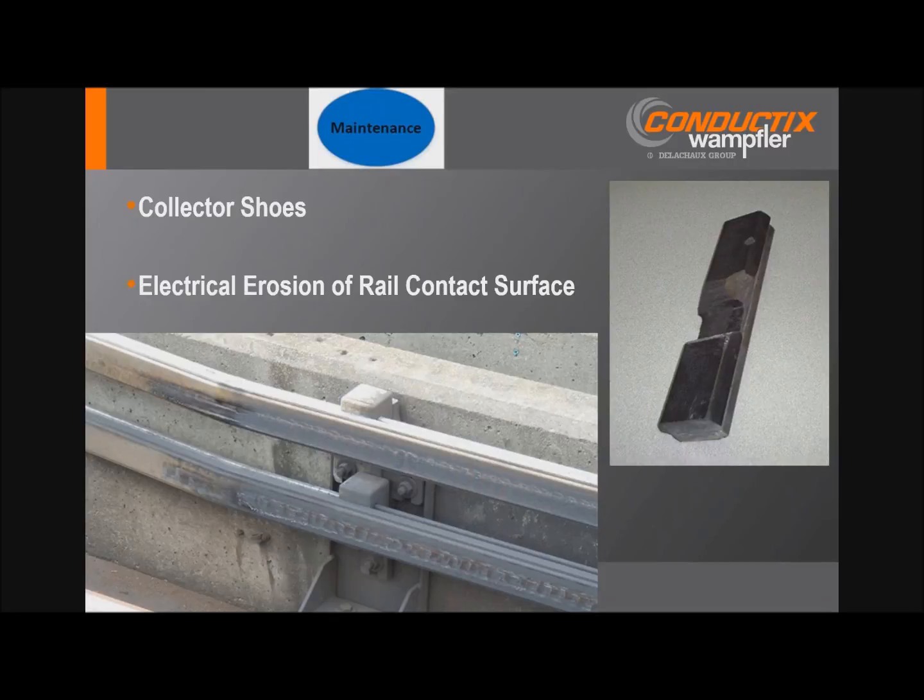And these factors include the number of gaps, switches, number of expansion assemblies, as I mentioned, exposure of the contact surface to precipitation, which will remove some of the lubrication, the speed of the vehicle, the guideway smoothness and geometry, even the collector shoe dimensions and collector design, and also the vehicle dynamics. So a lot of moving parts here.